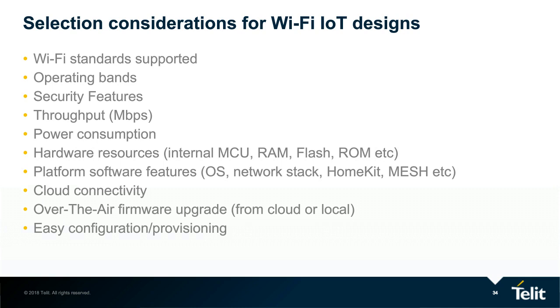Now, coming to security, it's a very important aspect of any product, as we all agree. As the market of IoT is taking shape, there are millions of devices getting added every day, and it is more important than ever before. Every solution provider offers security like WPA2 personal, enterprise, etc. But what is more important is how you are achieving it. Are the security aspects handled by a separate hardware engine, that means a separate dedicated crypto block in the module or the silicon, or achieved in software?